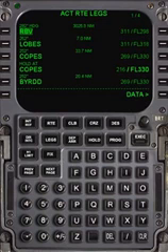These include scanning DME distance measuring equipment that check the distances from 5 different DME stations simultaneously in order to determine one position every 10 seconds. VORs, VHF omnidirectional radio range, supply a bearing. With 2 VOR stations the aircraft position can be determined, but the accuracy is limited.